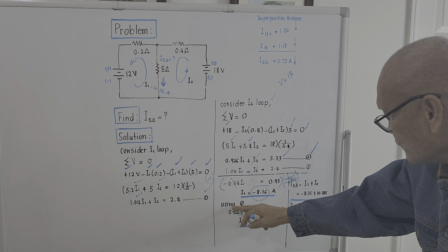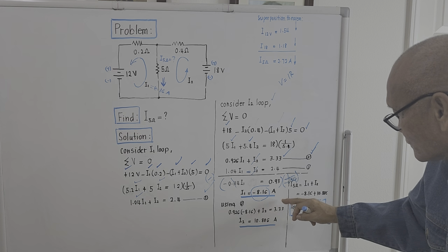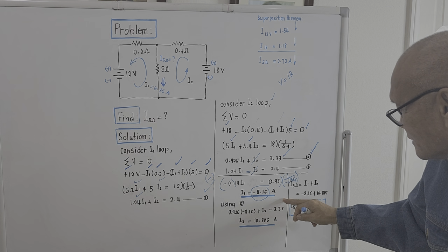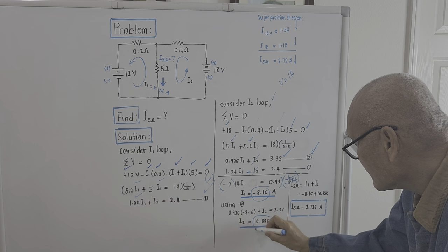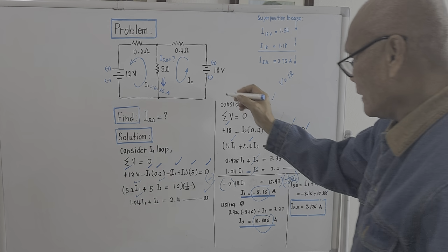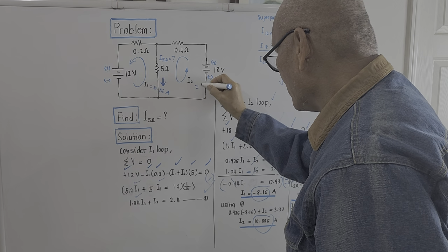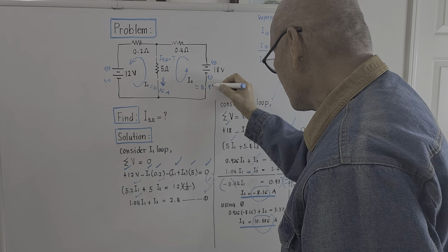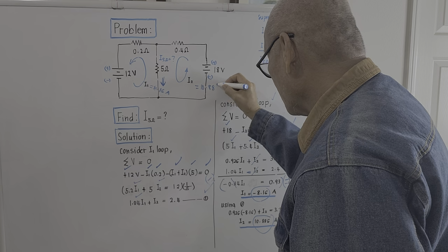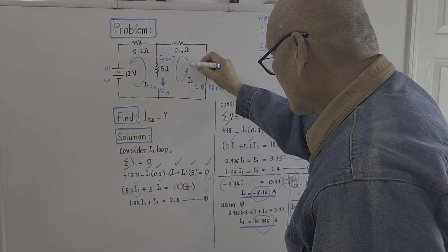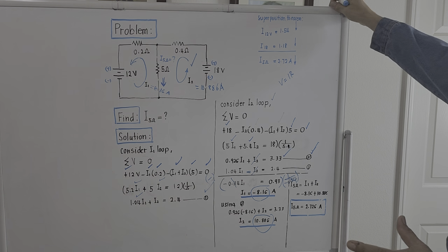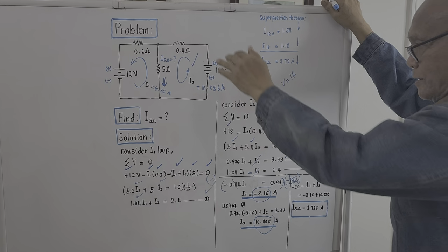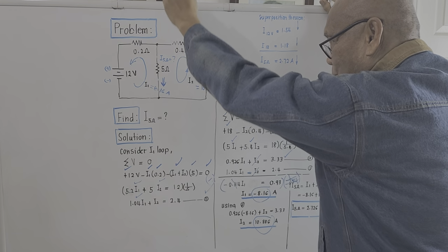8.16 times 0.926 plus 3.33, okay, it will add up to 10.866 amperes. So the value of I sub 2 will be 10.866 amperes. This is the correct direction. It's downward. Okay? So from the resulting value now, this is downward and this is upwards.